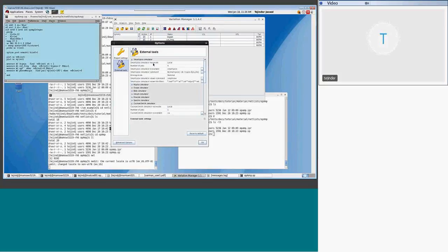Internal tools: we use the Smart Spice simulator. This is the executable, and this is the option we're using. In the background, this is in file node mode. Spice viewer is just SmartView. If you have another SPICE, you can modify those things accordingly. Basically, other simulators are supported too.